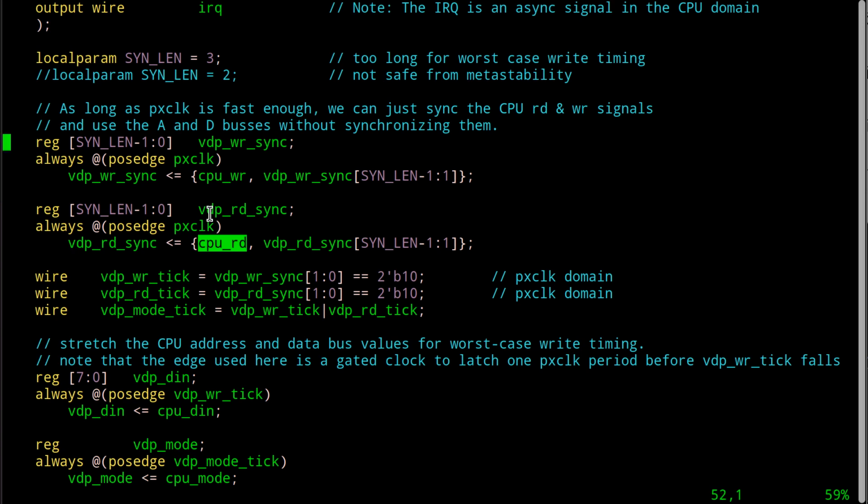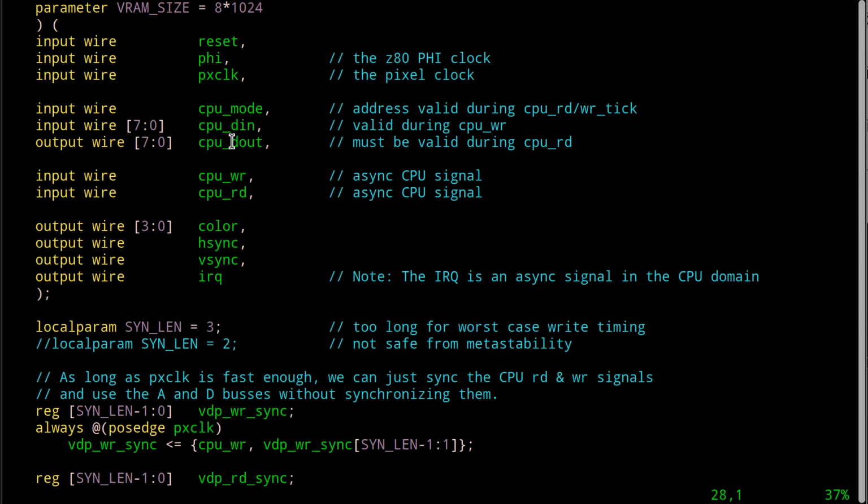All the stuff in these modules is active high logic, positive logic. If they need to be negative, they're flipped over before they come in here. And if I'm outputting something that's active high that needs to go out negative, it gets flipped somewhere else. That way I don't have to remember all this or put little underscore ends everywhere to remember what's high and what's low.